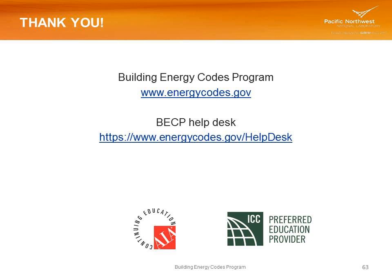So commissioning. Is commissioning required on both simple and complex systems? When is commissioning required? Yeah, there are some capacity limits. I don't know them off the top of my head, but if you look in Section 408 in IECC and in 90.1, it's based on square footage of the building. Once you get to a certain capacity of either heating or cooling, then you're required to commission the mechanical systems in the building.